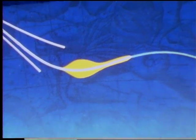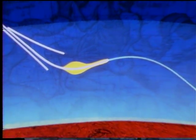During the remainder of the first control period until the skip, the landing footprint will be reduced to this area, about 690 miles long. Only minor adjustments of the trajectory can be made as the skip is approached. If all goes well during the first control period, the spacecraft and crew should be on a trajectory that can be safely controlled during the second entry.